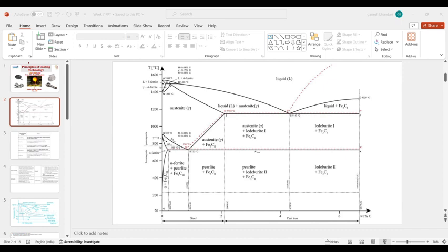Yeah, you can go with that also, or you can go with first heat treatment process, then surface heat treatment. Because if we go with surface heat treatment followed by normal heat treatment, what will happen, you have restricted your carbon or nitrogen up to a depth of 100 or 200 micron.